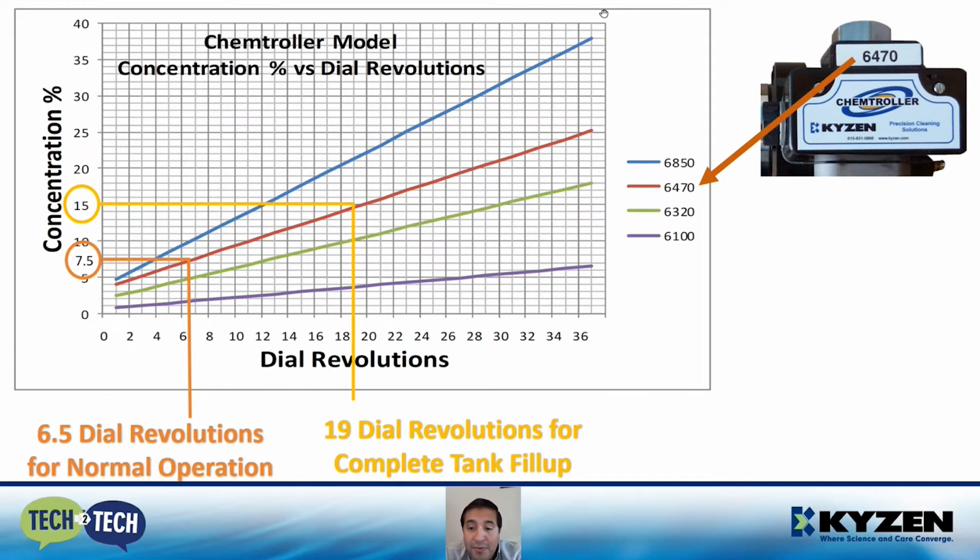The sum of all these factors will result in a variation of the consumption of water and chemical. You would usually expect to lose more water than chemical, but even if you have a continuous supply of both, like with the controller, it will always be adding a fixed amount. All the factors we just mentioned will contribute for a concentration to start moving slowly.